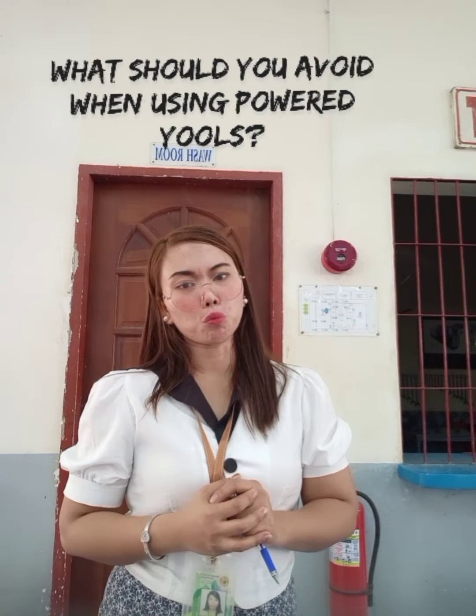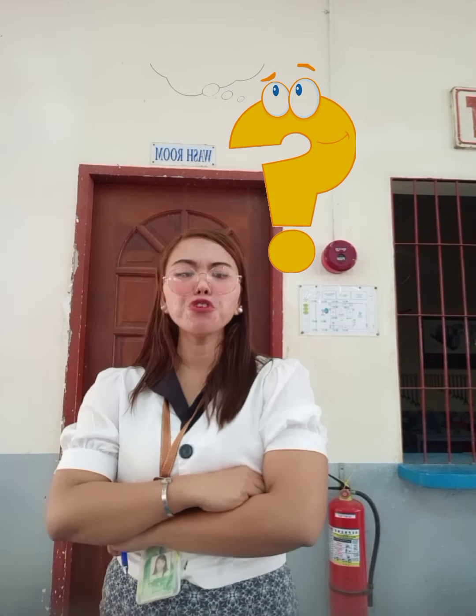And what should you avoid when using power tools? Of course, do not wear gloves, loose clothing or jewelry while using revolving power tools. Guys, take note of that one. Okay, so if you have long hair, you need to tie your long hair, and do not use a power tool unless you have been trained to use it.